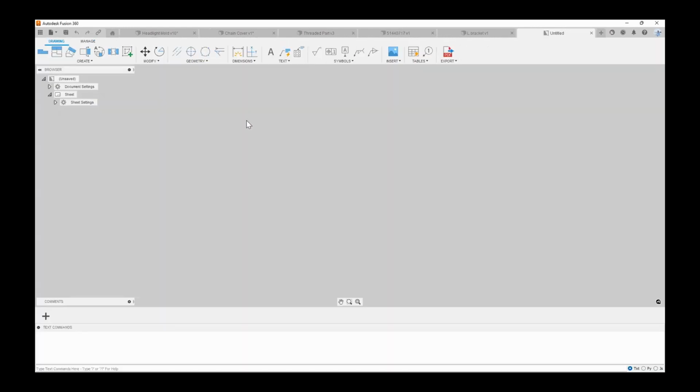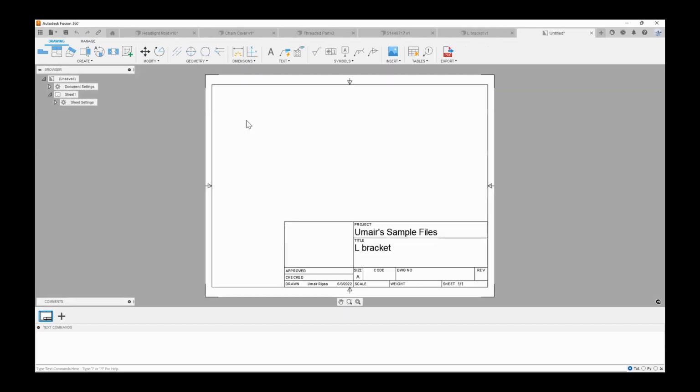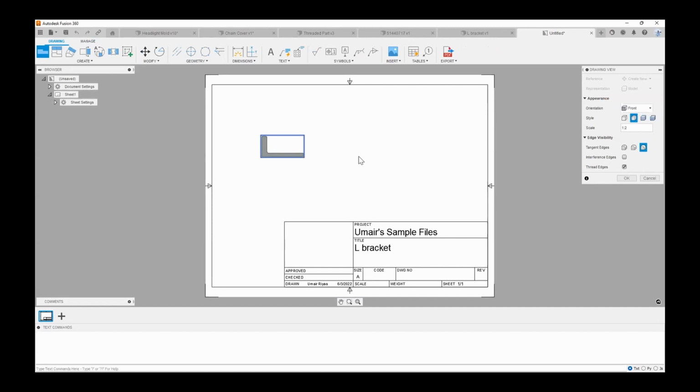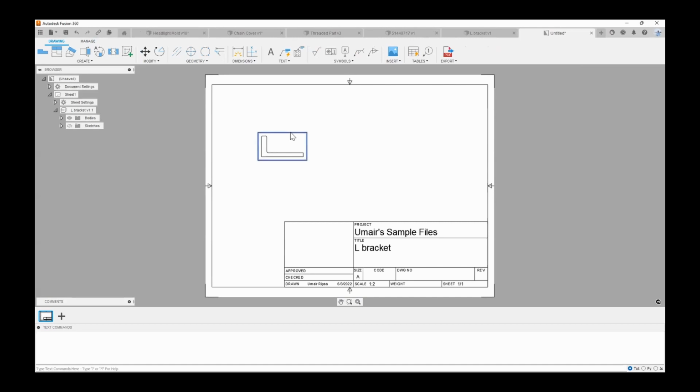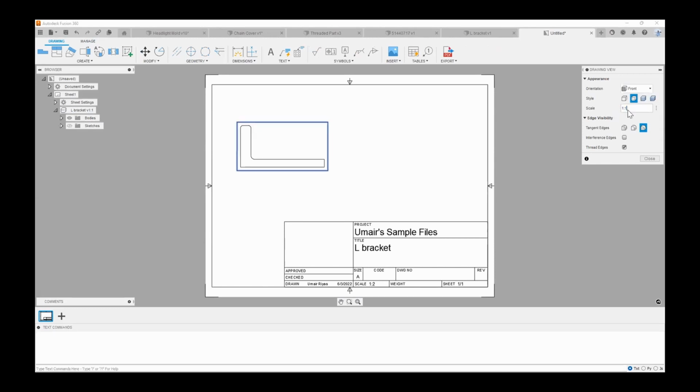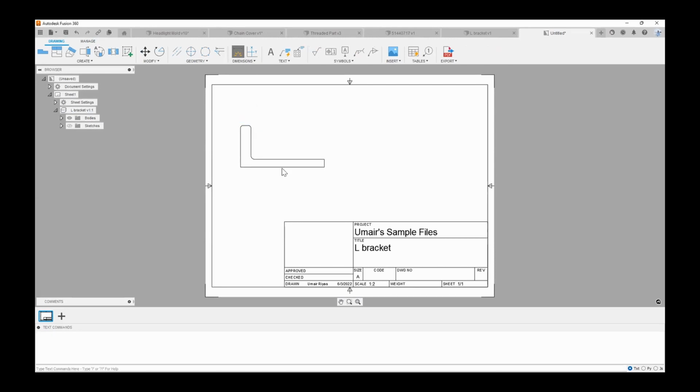So this is really where the magic of having Fusion 360 as one of those is a nice assistive software, because now, as you can see, very quickly, I can go ahead and just create a print, hit OK, scale this or do whatever I need to it, right? So just go ahead and say 1:1, drop a quick couple of dimensions on it, give a couple more views of it, and have this printed out, ready to go, and you hand it over to another machinist who's probably not as busy.